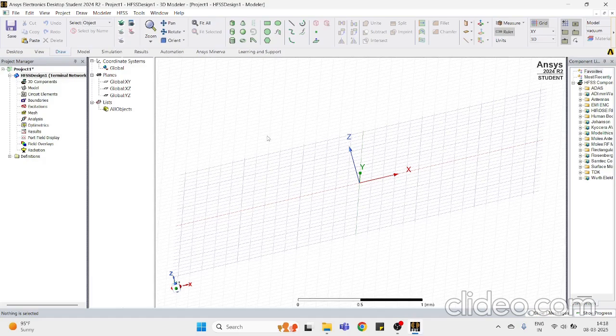So these are two different sets of experiments, and the basic flow that you'll be following, mainly for the stacked structures, is to first build a ground plane, and on top of the ground plane, you build a substrate layer, and on top of the substrate layer comes the microstrip line or the feed line, as you say. So this is the stacking, the layering, that I can say.